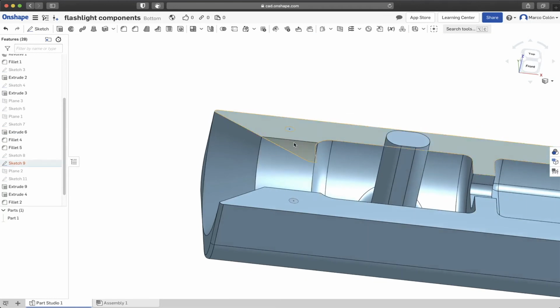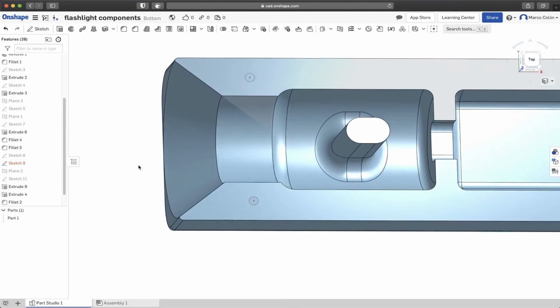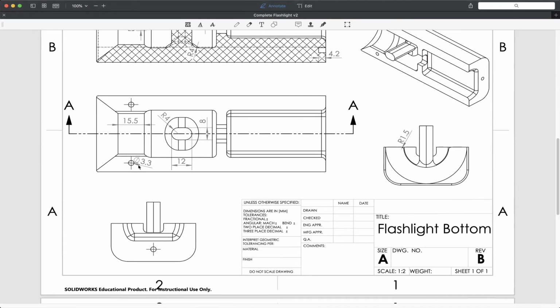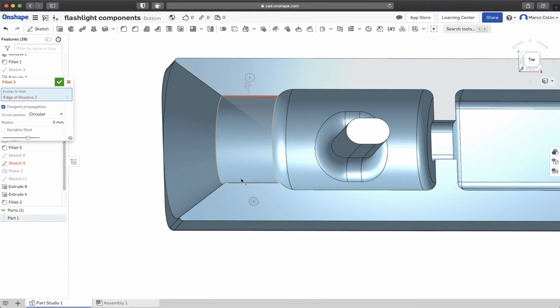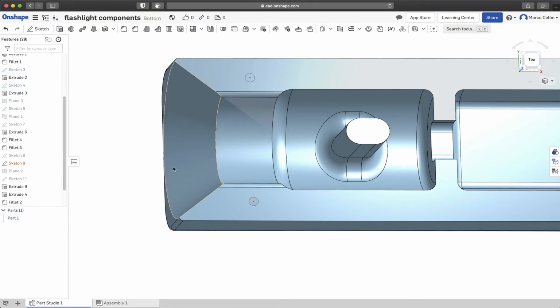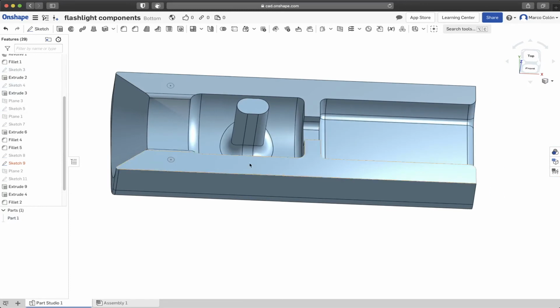Okay, that is just being the sketch line. Suppose we can do the fillets also. So here it's filleted at 1.5, same thing, made them slightly bigger so it could fit flush. So let's make those fillets there and there. Make it 1.5. And green check mark. All right, so the last thing we have to do is the holes.